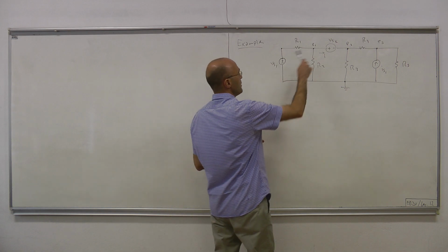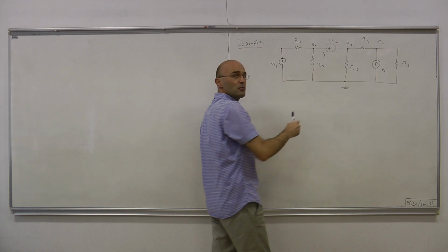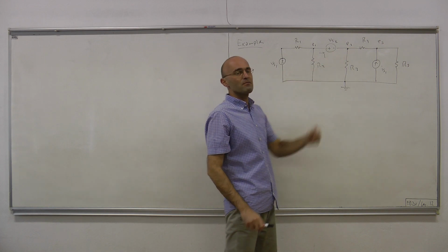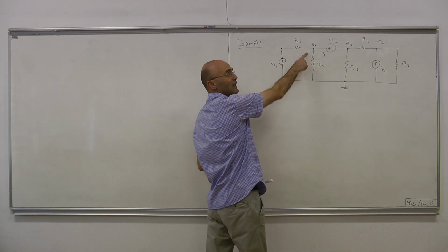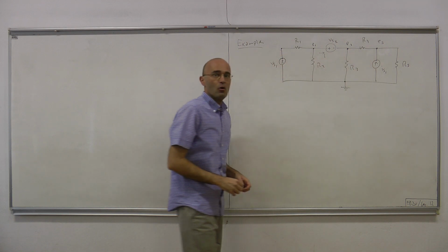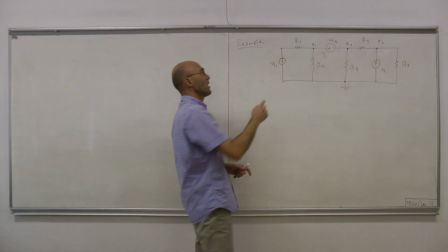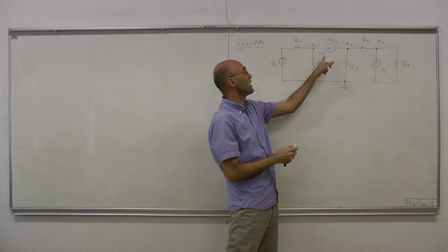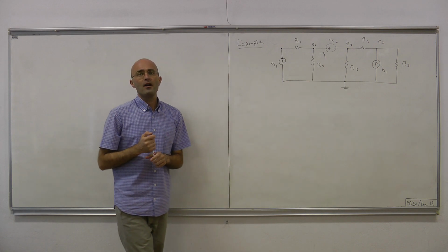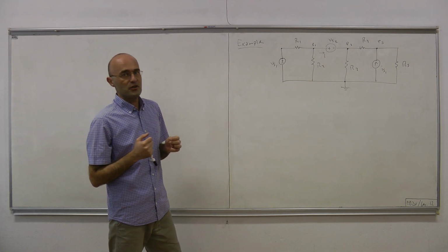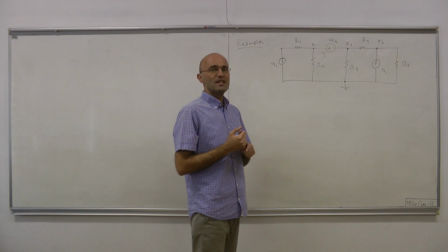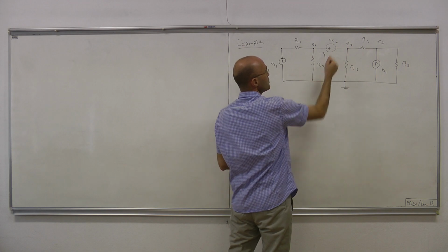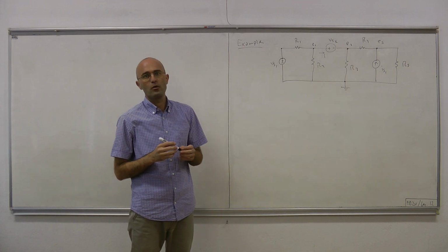So we just write minus I. We write KCL here, and KCL over there, so that makes 3 equations, but we have 4 unknowns, E1, E2, E3, and I. Therefore, we require one further equation, and that equation came from KVL, not KCL, through the constraint E1 minus E2 equals Vs2. That was our 4th equation.